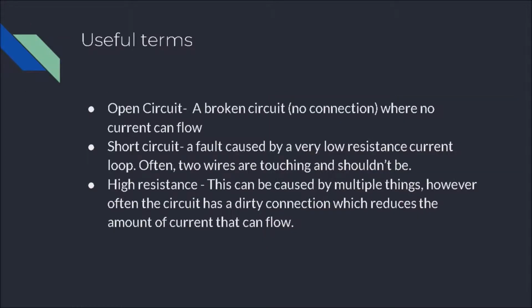Useful terms. An open circuit is a broken circuit where no current can flow. A short circuit is a fault caused by very low resistance. Often two wires are touching that shouldn't be. High resistance can be caused by multiple things, but often the circuit has a dirty connection which reduces the amount of current that can flow.